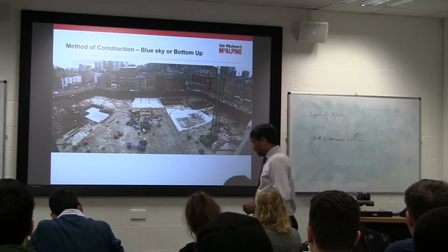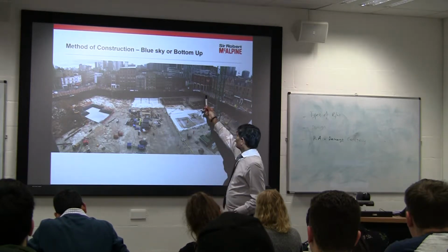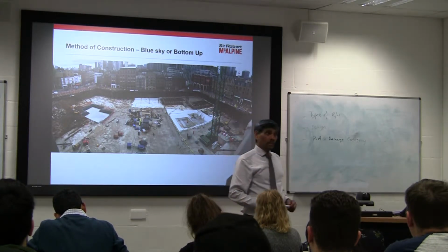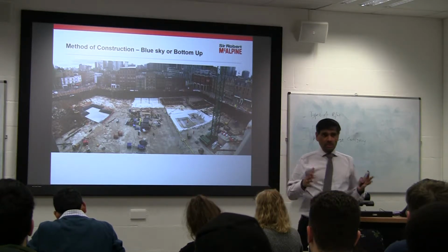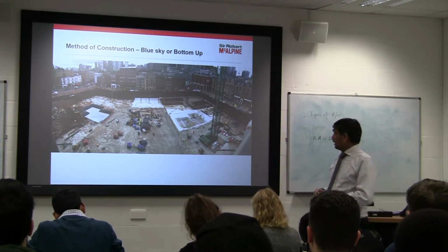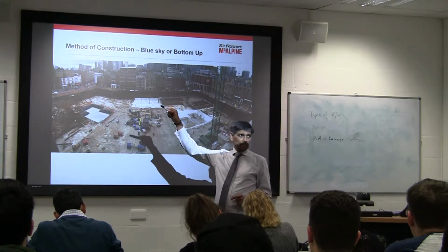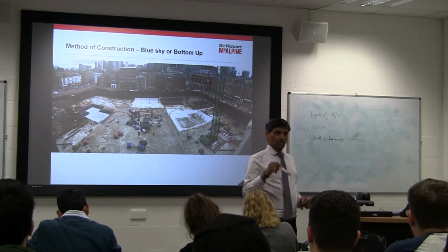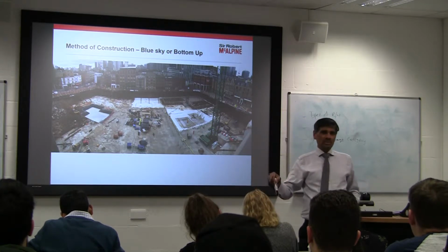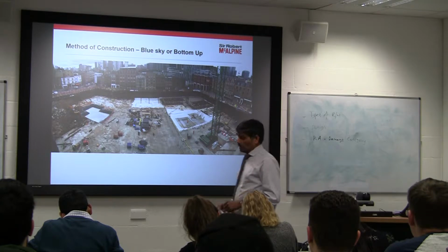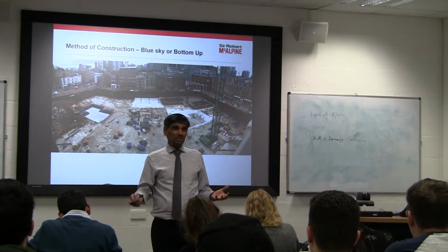And in London, there are restrictions on how many lorries you can take on those highways in the peak hour moments. So the construction hours between 8 to 6, whatever 8 hours are stipulated, the council or the local authorities impose planning conditions that you cannot take more than 100 trucks out. Every truck carries no more than 10 meter cube of muck, so you can only take 1,000 meter cube.